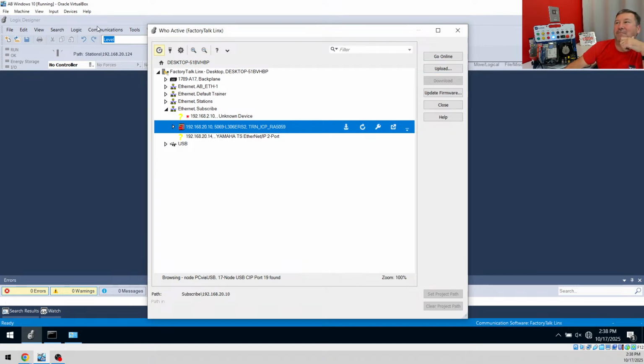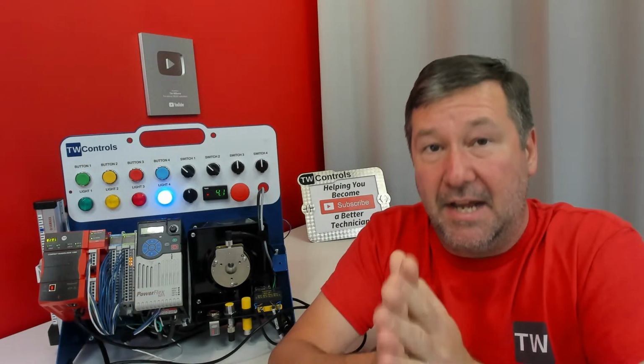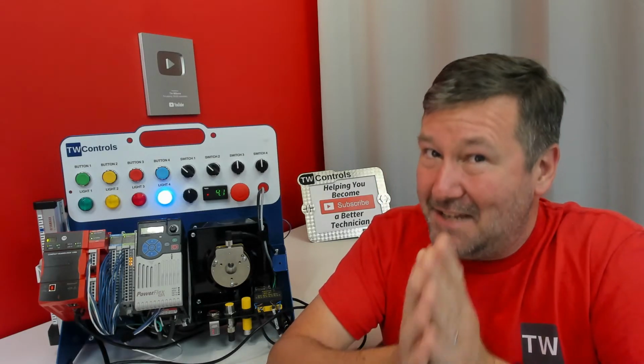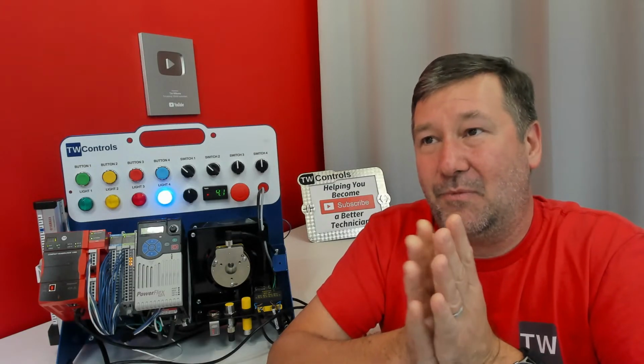And this is why I think this step is so important. Notice earlier I said we had no file open. So here's kind of my rule: if you have never been connected to a PLC, do not have a file open, not even a blank file. And this is so important because Wednesday of our class, that's the day that they reverse engineer an unfamiliar machine.